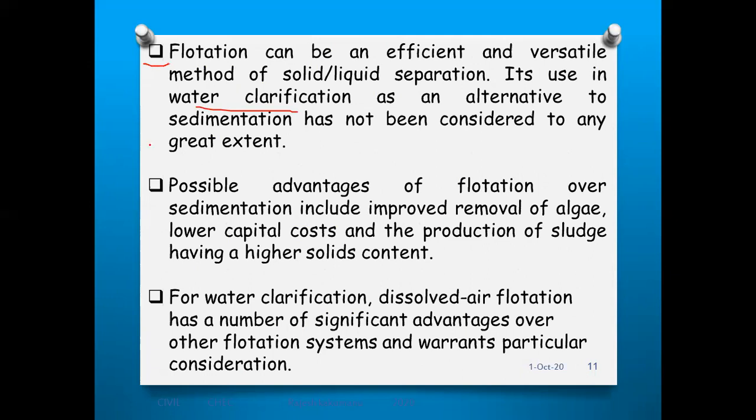Next, second point. Possible advantages of flotation over sedimentation include improved removal of algae, low capital cost, and production of sludge having higher solid content.